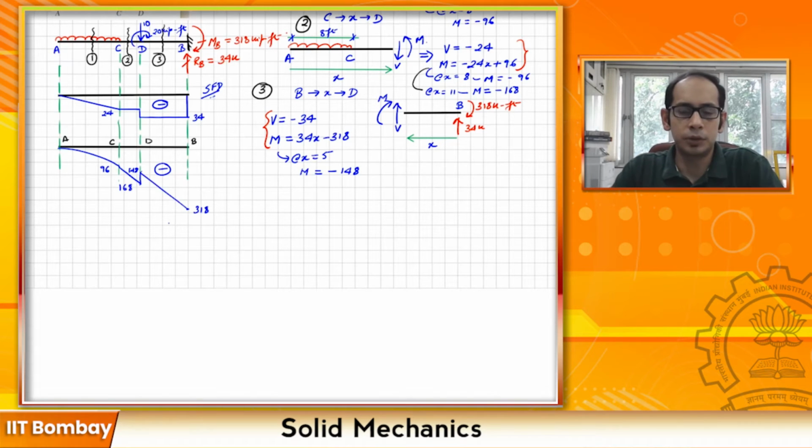The problems that we just solved in the past several examples, if you think about how you did that, you had the beam and the load, and you cut sections at the different points. This is the classical approach of drawing bending moment diagrams and shear force diagrams, also known as the method of sections. It is quite intuitive if you think about it. When you had the beam with loads at different parts, you took the sections, and after that you wrote the equations for the shear force and the bending moment for the different sections. Then you went from establishing the equilibrium from left to right or right to left, whichever was convenient, and eventually from those equations you drew the shear force diagram and bending moment diagram.